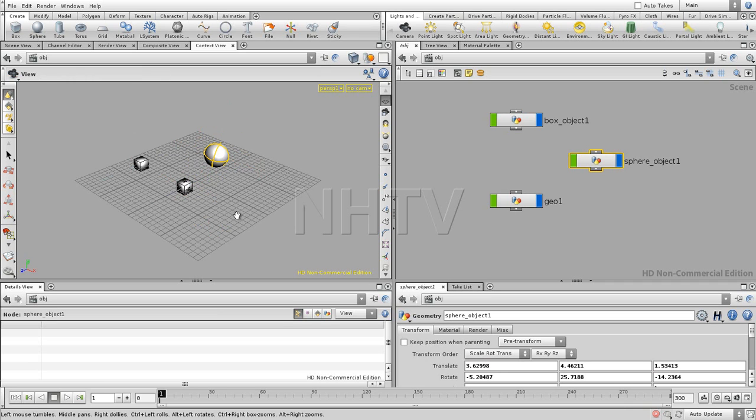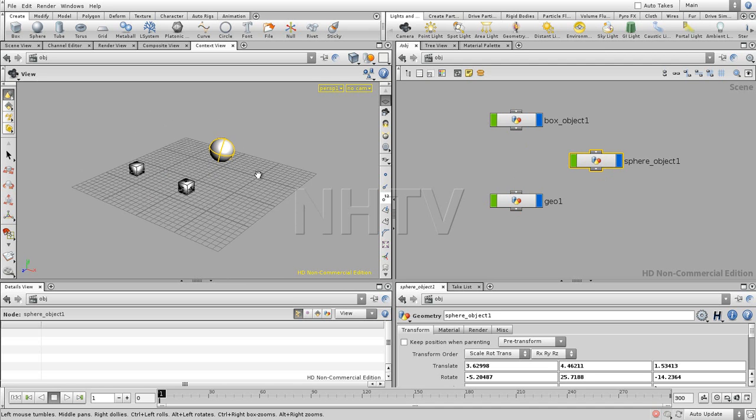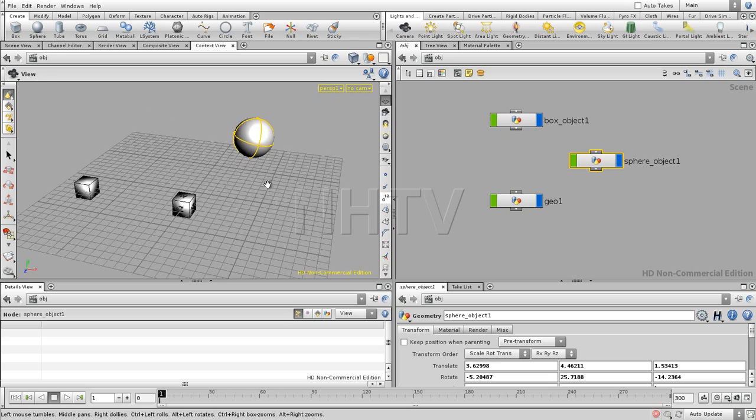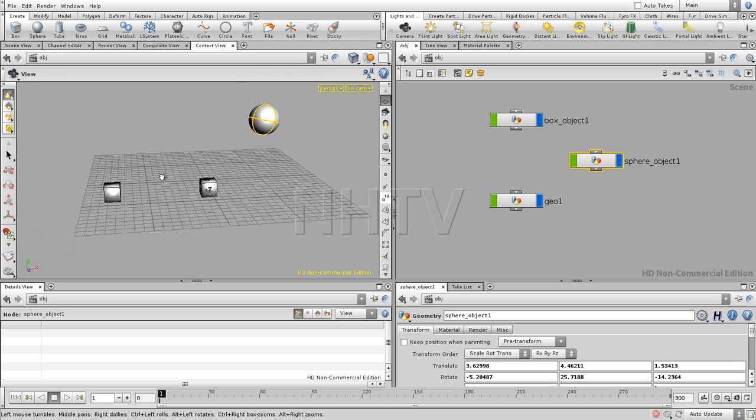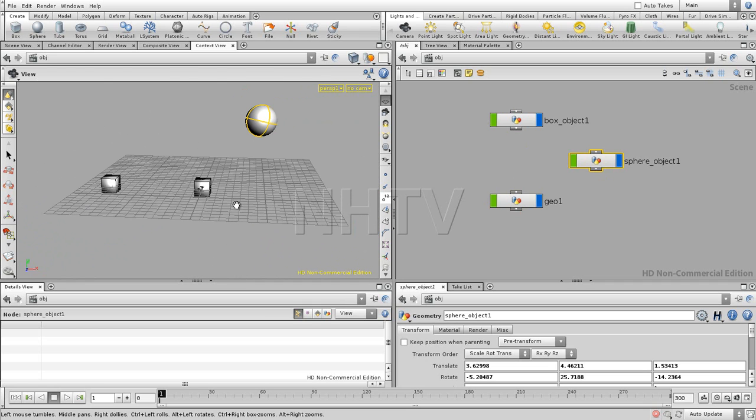Now we can also make sure that all these control handles are not active anymore. If you press Escape, then you see there are no handles there, no matter what kind of object that we select, and we can't select any object in the viewport anymore. You can't just click on it. So what you have right now is that you can just move around in the viewport and you don't have to press the space bar. Now if we press Enter again, then you activate the controls again. So the combination is Escape and Enter.